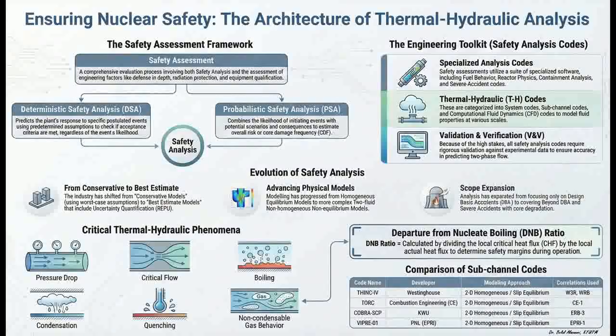It is, but that efficiency has a strict thermodynamic limit. And this is the critical threshold in thermal hydraulics. The slides refer to it as departure from nucleate boiling, or DNB. Also known as critical heat flux, CHF, or simply the boiling crisis. Reaching the boiling crisis is the exact scenario the safety systems are designed to prevent. Because the danger of critical heat flux comes down to the stark difference in thermal conductivity between liquid water and vapor.